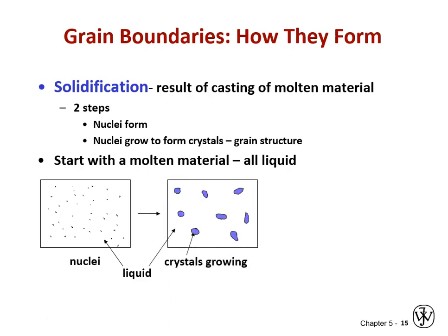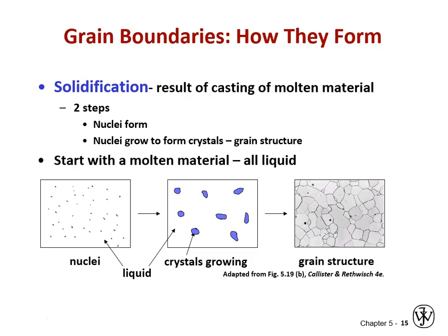They'll grow in size, and each one of these is oriented in a completely different direction. And eventually they'll grow together, preserving that random orientation. And so the planes between them, and what you're looking at is a flat cross section, so the lines surrounding those grains are actually surfaces. So those are grain boundaries that you're seeing. They're very energetic defects because there's a lot more void space, and the angle between the different grains, the crystals, is random and sometimes is very extreme.